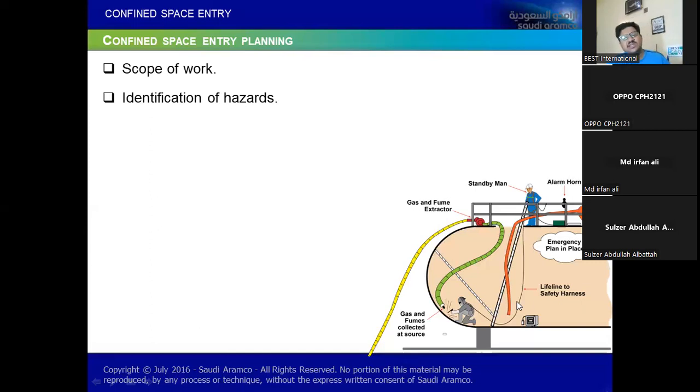And disconnection is mostly applied when the project is long term, like maybe for 1 month. Aramco has criteria like: first permit for 1 operational shift. Then if you still need to extend, it can be extended up to 24 hours. You can get it renewed for 1 more shift, in other words. And an extended permit may be extended for 1 week or maybe for 1 month, but the maximum duration is 1 month.